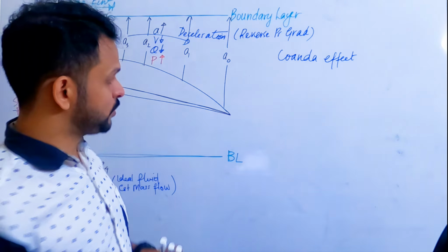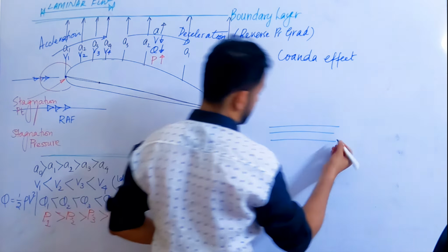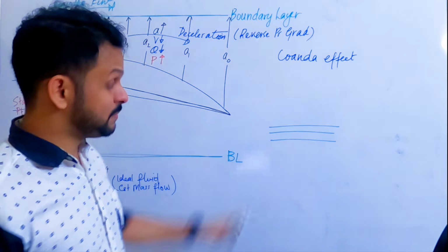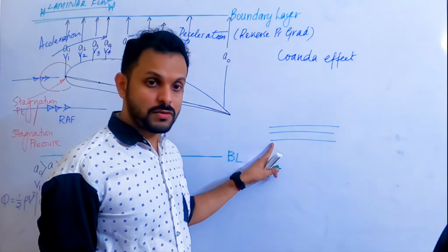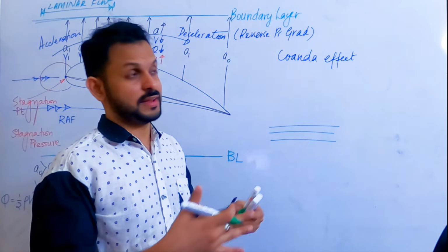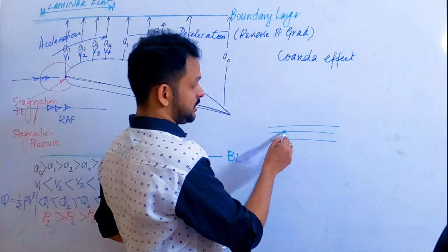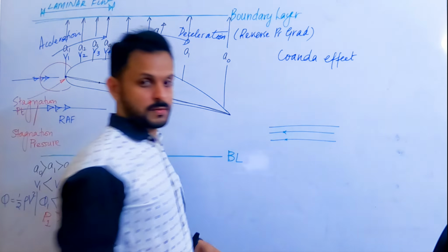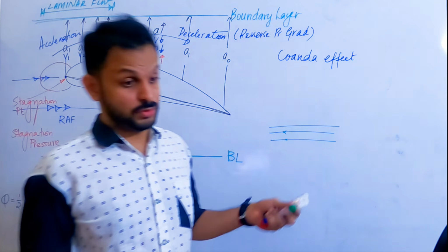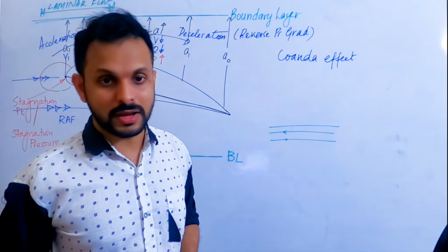So laminar flow is a flow that is more streamlined. You have different layers like stream tubes and streamlines present, and they flow one over the other. The viscosity effect is comparatively lesser. It's more like an ideal scenario, which does not really happen in nature, right? The lines do not cross each other. So it's more like an ideal flow, as I told you, like a march past, line by line. They do not cross, they go in a line. That's more like a laminar flow.